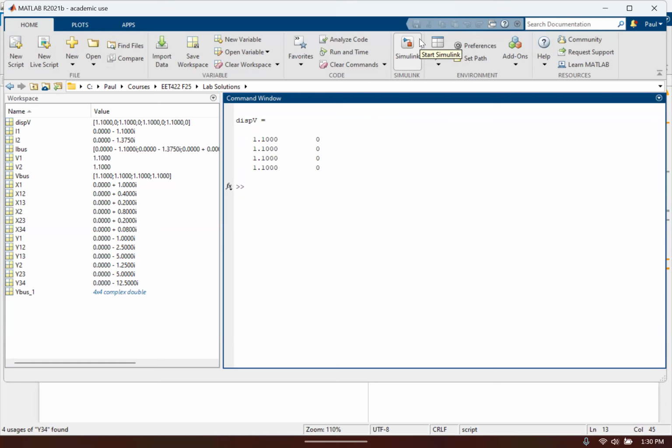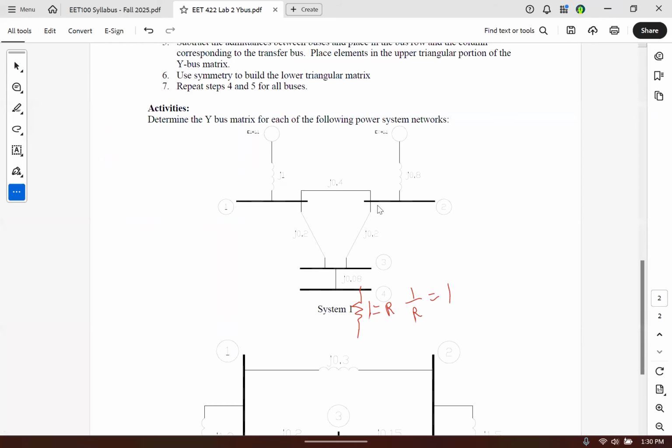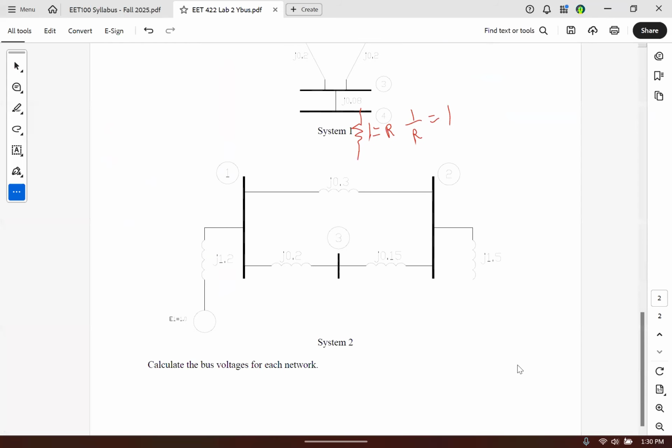And if you look at the second system, what do you know? Tacked at the end of bus 2 is something that is hanging off in the air. A j1.5, we'll call it ohms for now, equivalent load. So we have to include the fact that there is a load there. So in the second problem, our voltages are going to be different than the first problem.